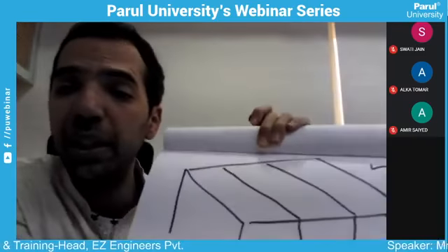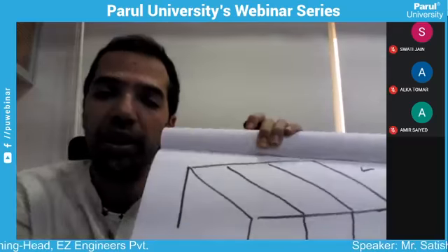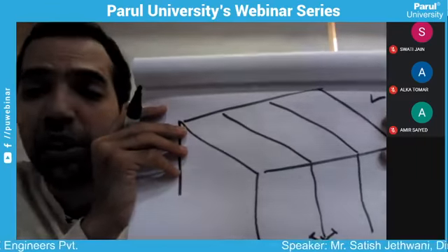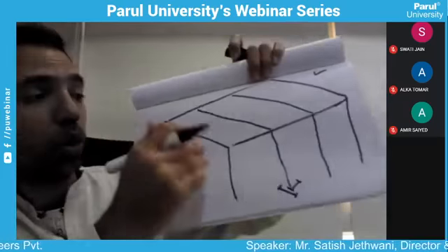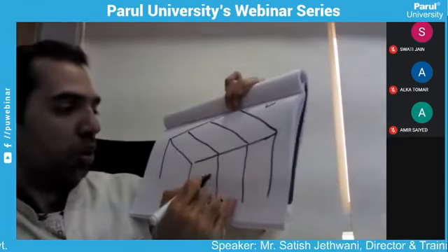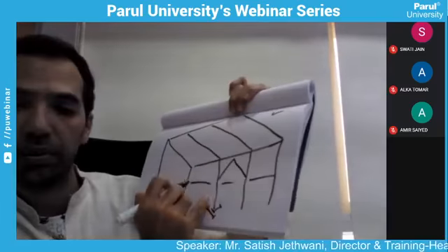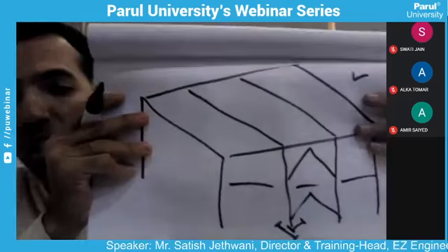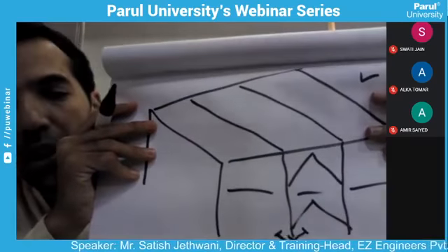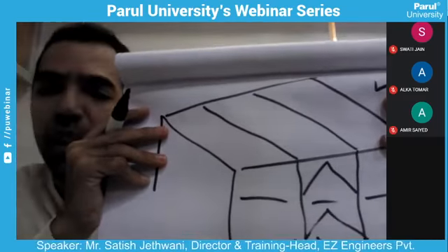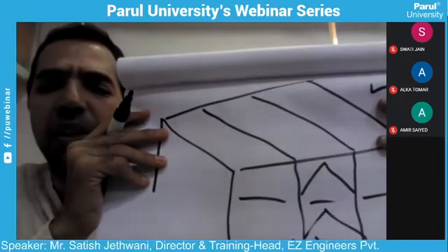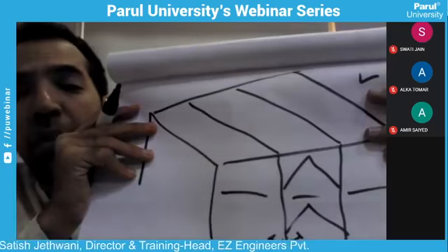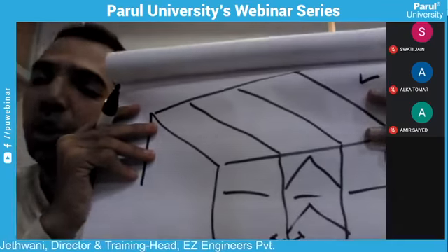It cannot be decided by any of the software in the world. Understand friends, if you learn STAAD Pro, if you learn ETABS, if you learn SAP, in that you have to give this input. Where will be the bracings? That you have to decide as a structure engineer. You can model plan bracing, cross bracing, vertical bracings, knee bracings in STAAD Pro or ETABS software. But where to model, that has to be decided by you only.